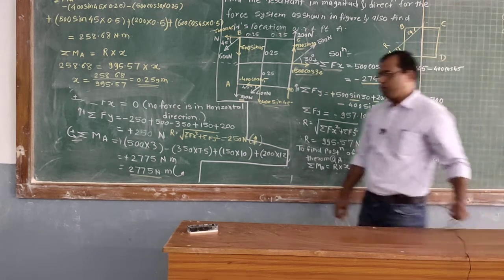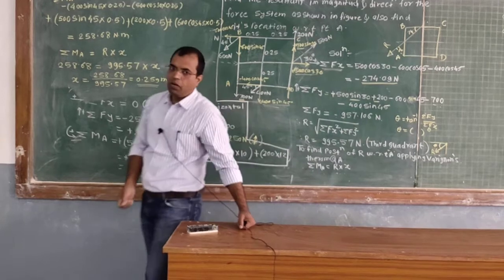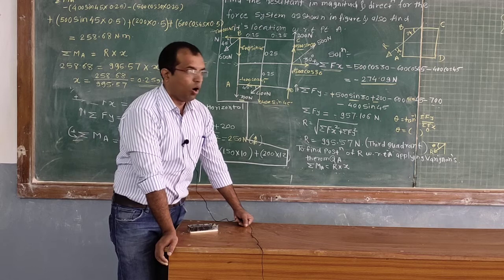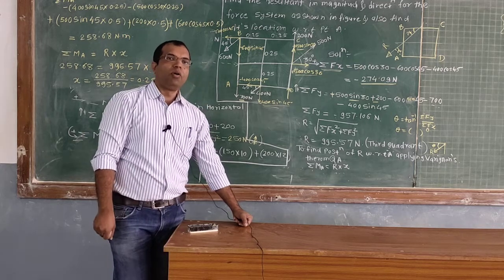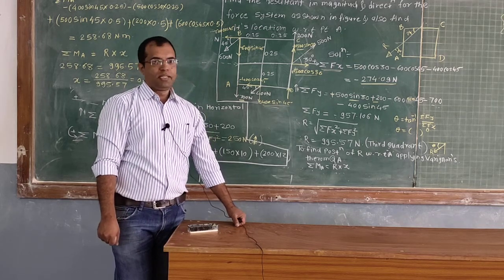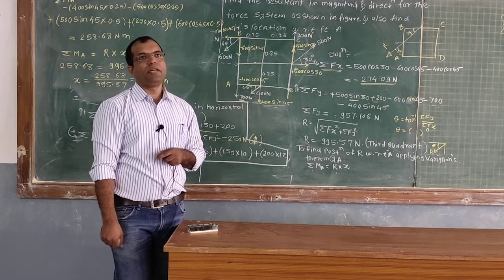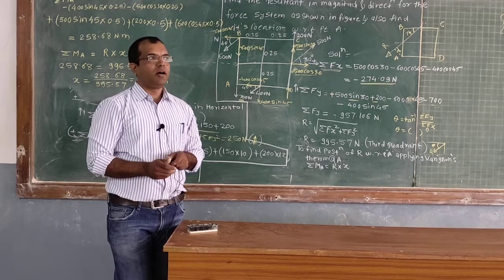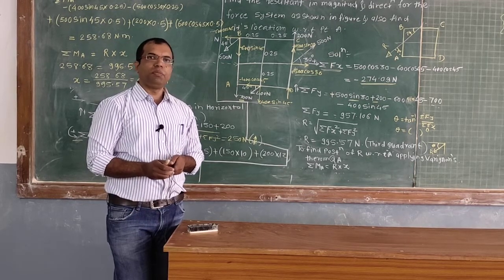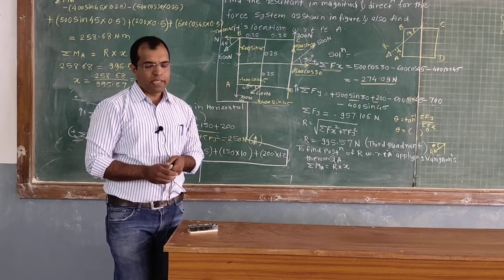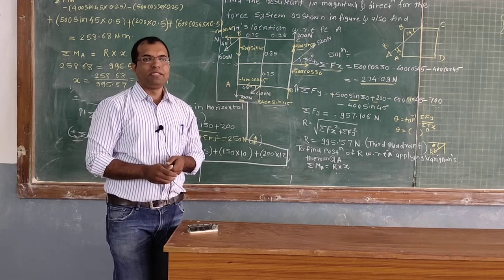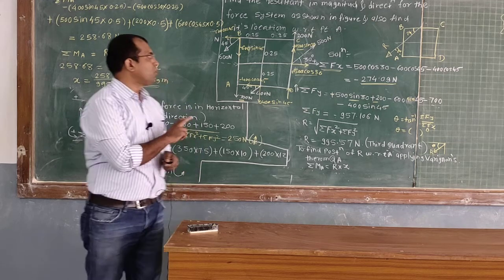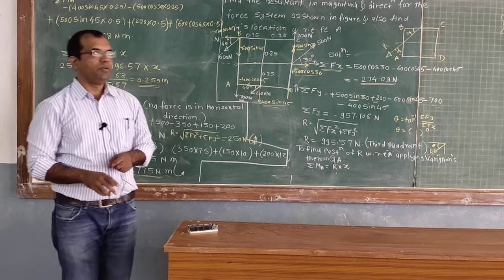Okay. So today we have learned how to find the moment, how to find the resultant of a parallel force system, as well as how to find the location of the resultant. The location of the resultant is found by using Varignon's theorem. You must take care of sign convention while writing the equations of summation of Fy, summation of Fx, and the equation of moment, as well as the equation of Varignon's theorem. These two problems we have solved today. So thank you very much.